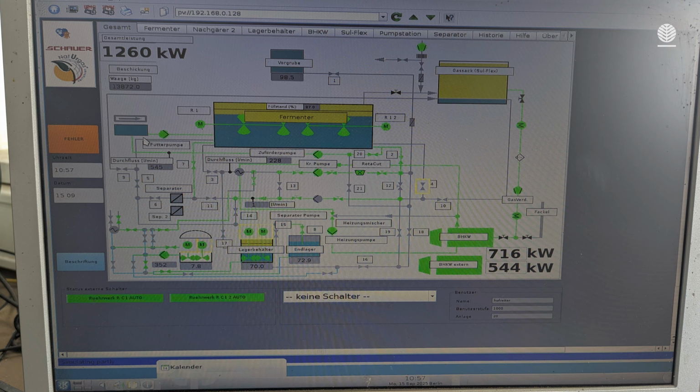So can you convert into raw biogas by any chance, Rückert? Well, it's around 550 to 600 cubic meters. I'm just looking at the flow meter for the gas, but it's a proof. If the engine is running, it can only run on gas. It's 100% running on biogas. So you can see one engine is 716, the other is 543. The gas holder is still full, because it's totally yellow.